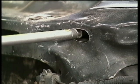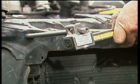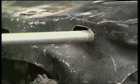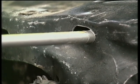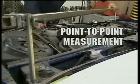To find the center measurement, measure from the inside edge to the other inside edge. Then measure from the outside edge to the outside edge. Add these measurements together and divide by 2 to get a center measurement. Point-to-point measurement refers to the shortest distance between 2 points.